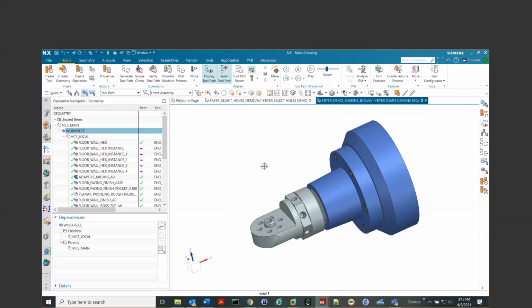Since we're using Shopfloor Connect to download the program to the machine, anything that you edit at that level may not be privileged or allowed to go back into Team Center. That's a customer default, whether or not you want your hand-edited program to be able to go back into Team Center or not. By default, I believe it is turned off.